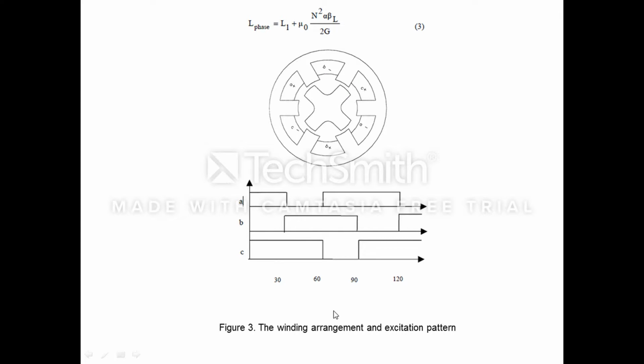Let's talk a little bit about the MCSRM model with the finite element method. We will look at the equation, so now let's turn to the model with finite elements. The examined model of the switched reluctance motor is a three-phase 6/4 motor, which has 6 stator and 4 rotor poles.